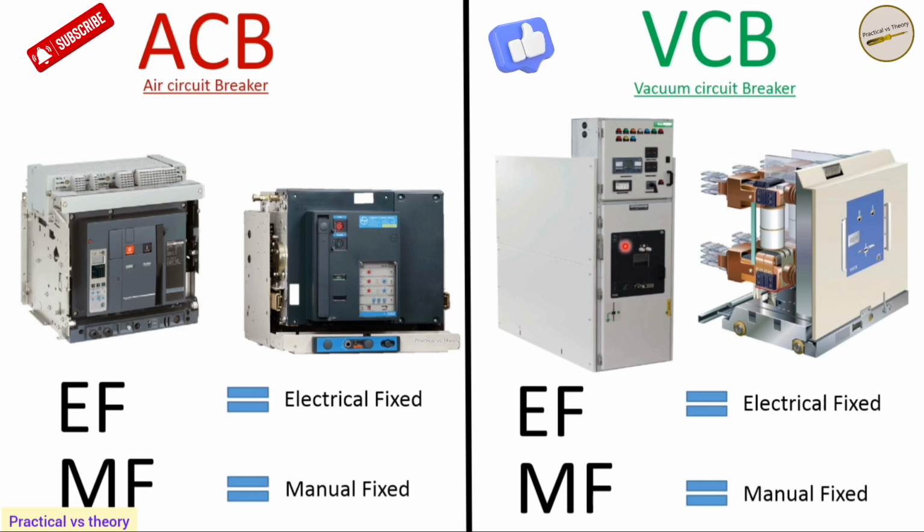The output side is also going to 11 kV. Now, I'll have to cut off the input supply first, only then can I touch it. How do I do that? I'll have to earth it first. Now, let's assume this breaker is the input, and this breaker is the outgoing one. Its input breaker will have to be opened first. Now there are 3 more breakers between that input and the outgoing breaker of the output. When those 3 breakers are opened, then only there is the 4th breaker. So this means the supply of all 4 breakers will be cut. Okay, so this becomes a bit costly. At that time the downtime cost is more in EF and MF.